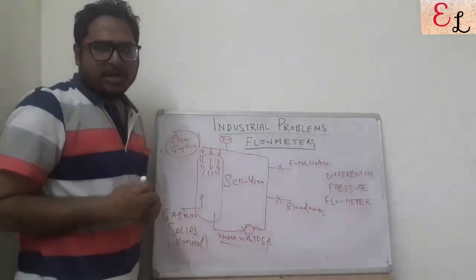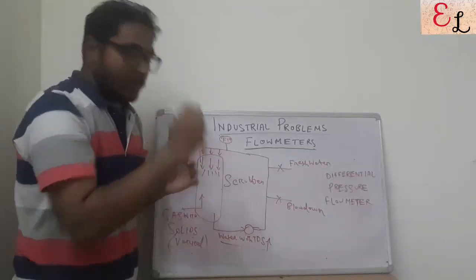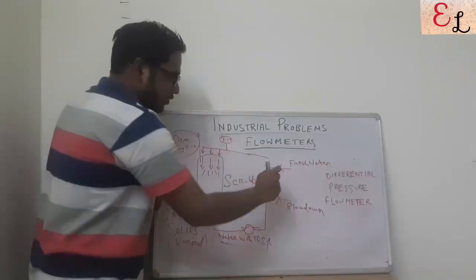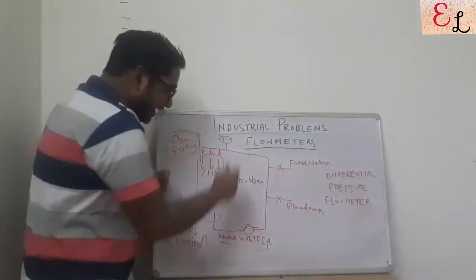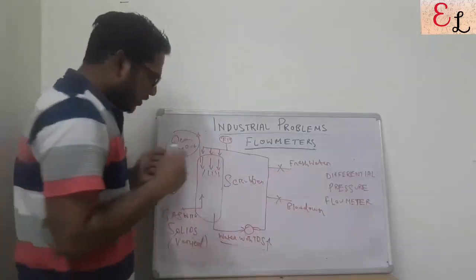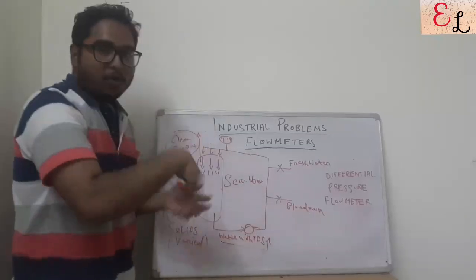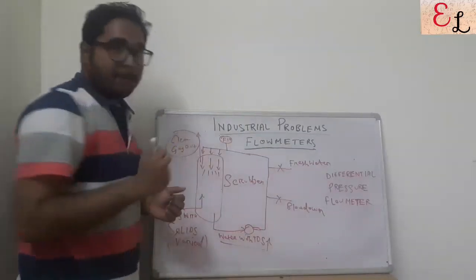And this is done at regular intervals. Once we measure that the TDS is increasing and has gone beyond limits, we need to blow down and introduce fresh water. Even if it is a continuous process, with continuous blow down and continuous fresh water to maintain the TDS in the system, still the TDS will vary because the gas dust load is varying in the system. So a varied amount of dust will be absorbed by the water and will be flowing in the system.